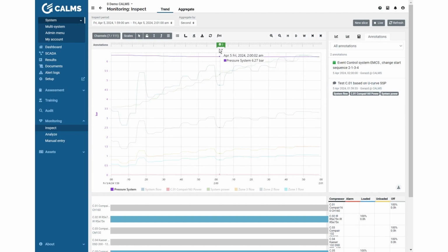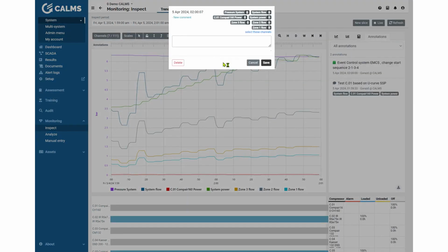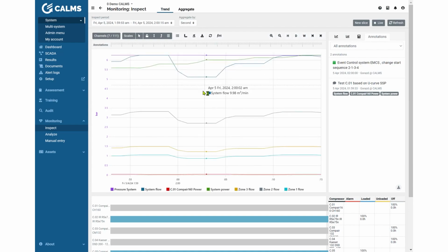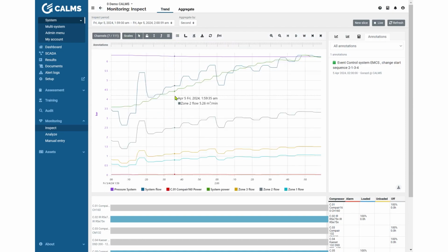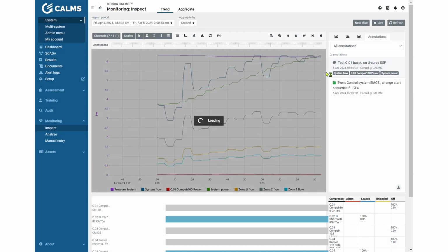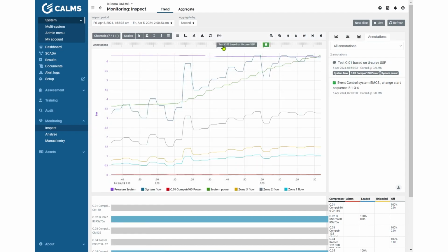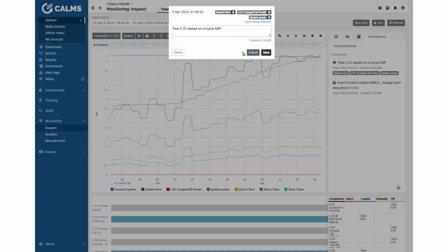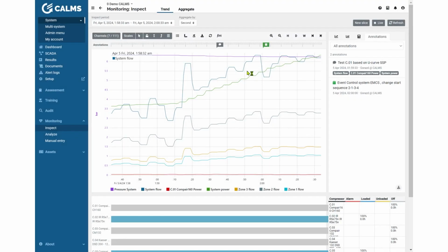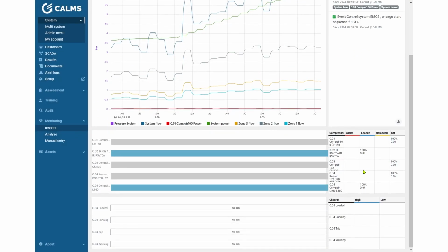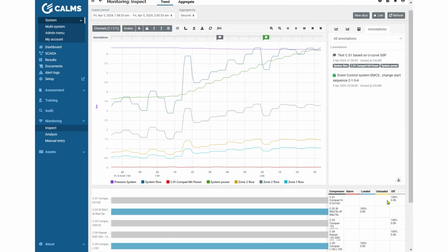One is the manual comment here inside, so you can zoom in here, and you'll be able to see one comment, or maybe go back, and you will have here another comment which was here. You can click here, you will get the details. You can delete the comment if you are the owner of the comment, the time, relation to the signal. And below you have also digital inputs, which will show you the percentage and how many times the unit start, stop, and how many percentage of high and low state, 0 and 1s.